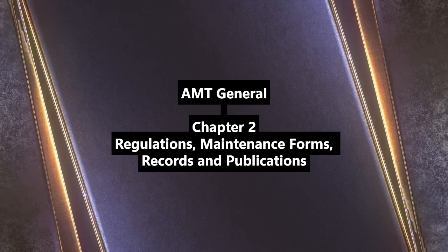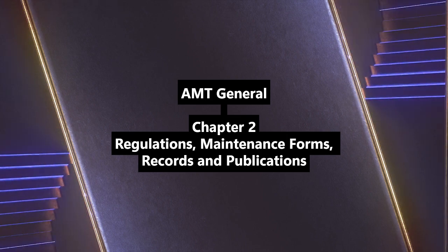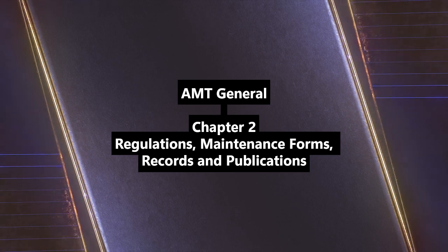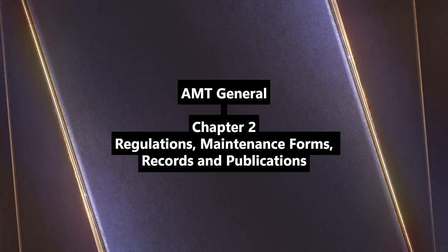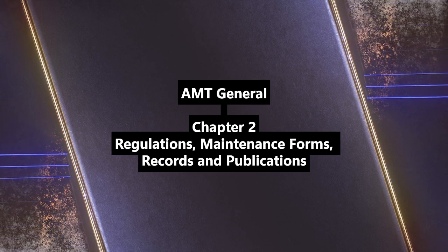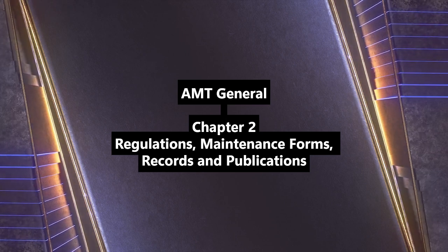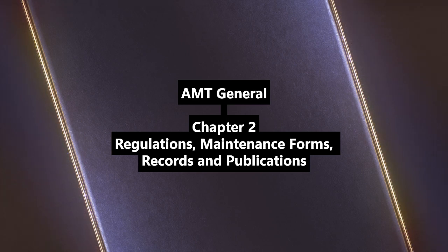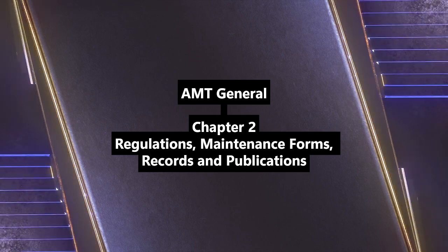The aircraft registration. Form 8050-1 application leads to AC Form 8050-3 certificate. Required for U.S. owners. Pink application copy or certificate must be on board. Correct. Radio station license generally not required anymore for domestic U.S. flights since '96. Was an FCC requirement for international.